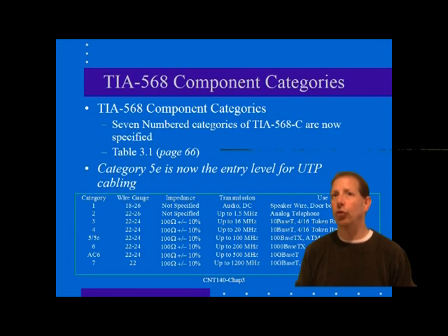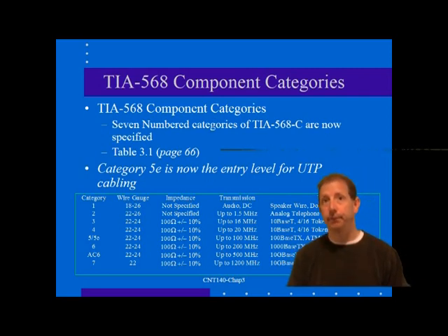Unfortunately, users soon learned that the cable needed to have specific characteristics, such as a minimum number of twists per foot, to work properly. The cable needed to meet certain performance levels that varied with the application, and a cable vendor's rating systems, supplemented by Underwriters Laboratories testing, eventually was incorporated into the 568 cabling system.